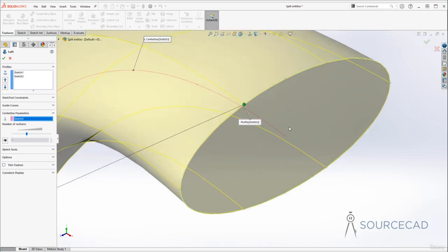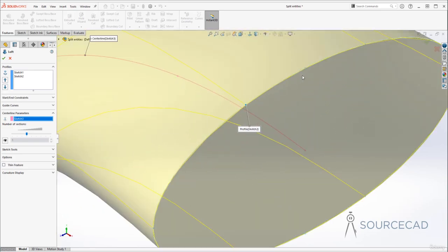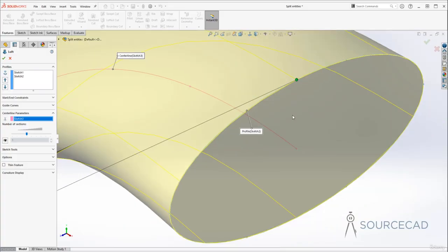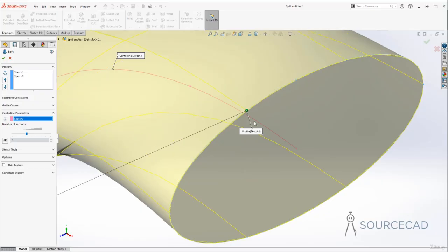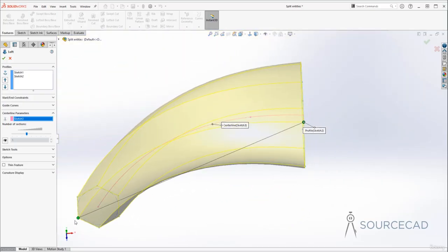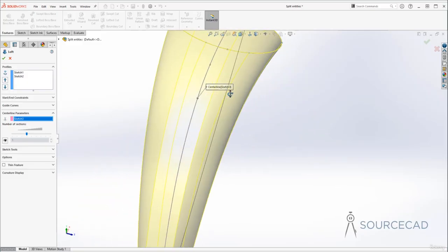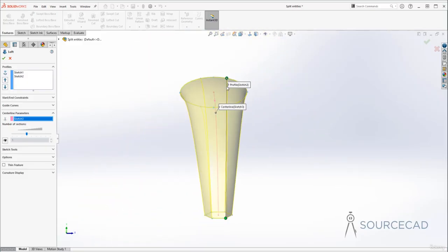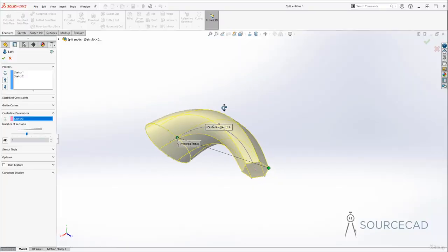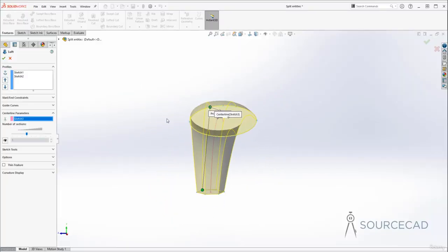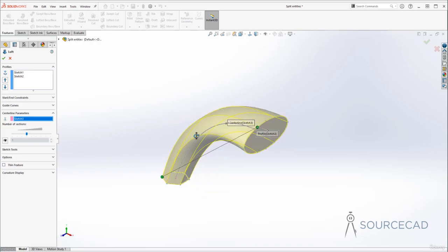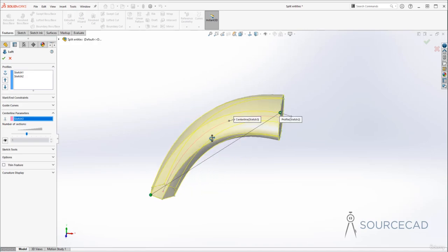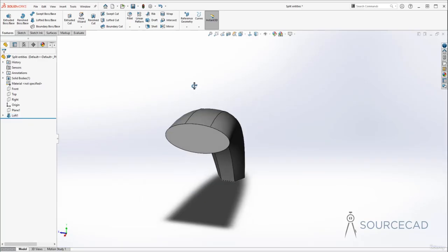Now to control the shape of this loft properly, you can also move these anchor points. So you can just move them the way you want, and you can also see these split points. So it is now clearly visible and you can just move it wherever you want. So in this case, I just want to move it here so that all of these are completely streamlined and in such a way that it is completely uniform in shape. So from all the sides, it is completely touching the other profile with equal segment length. All right, so that's the segment tool. Now I'll click OK, and here we are, we've got this profile.